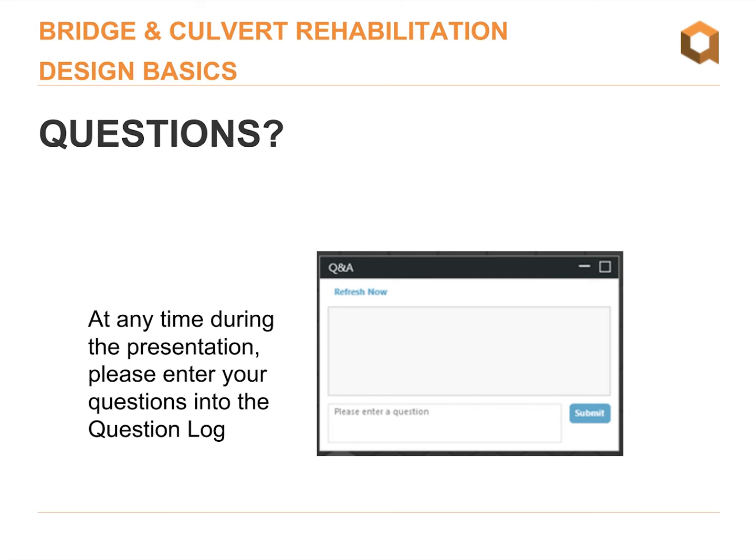Just to elaborate on that a little bit, in terms of what we provide our seal for. We are designing these in a structural capacity. So of course we design it for the final installed condition with the fully grouted annulus for the given live and dead load. So that's essentially what we stamp the drawings for.